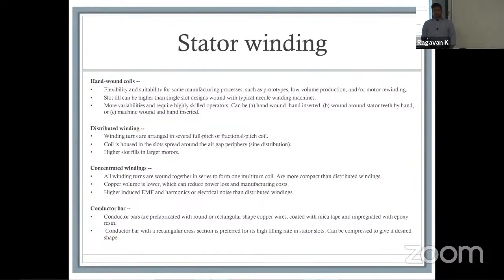Concentrated coils, has anybody here dealt with a concentrated coil, or in most applications have you always had distributed? Anybody here who's used concentrated coil before? If you have done any work on switch reluctance machines, you will see concentrated coils used quite a bit, right? Because they are individual phases. Each pole has a coil wound around it. There are real benefits. If one coil goes out, the other coils are not affected.